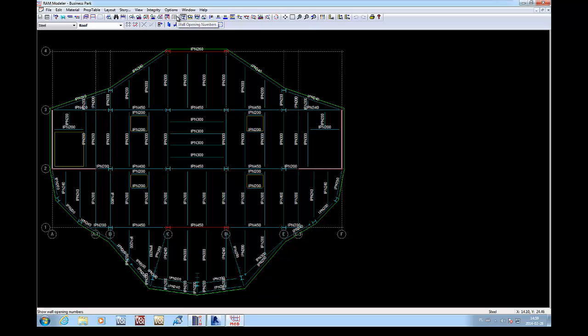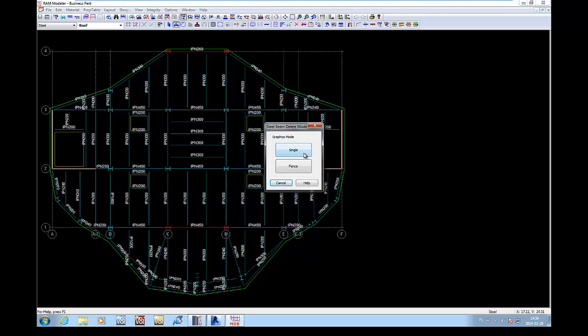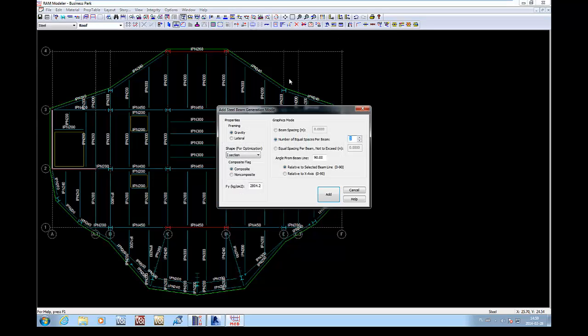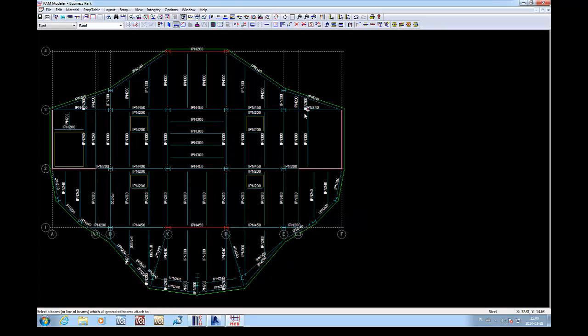And now to show the two-way integration, we can change this part of the model and add some beams here in RAM structural system. So first of all, we're gonna delete those 2 ones and add framing between the wall and beam. It's gonna be an I section. And the beams are gonna span from here to here in this direction.